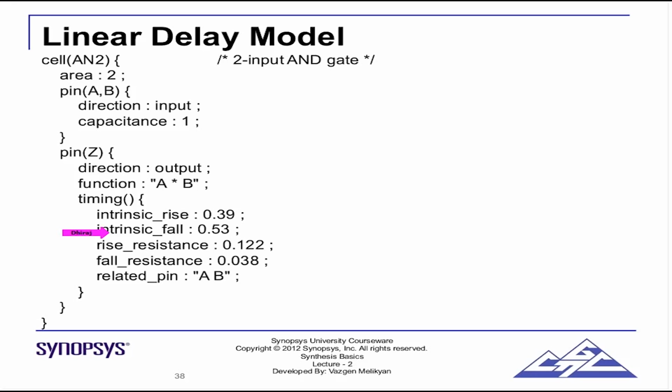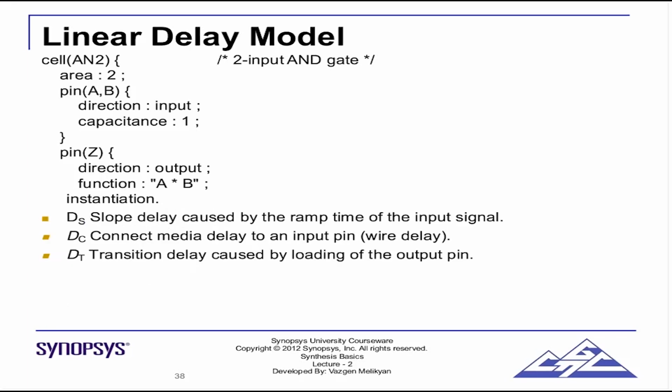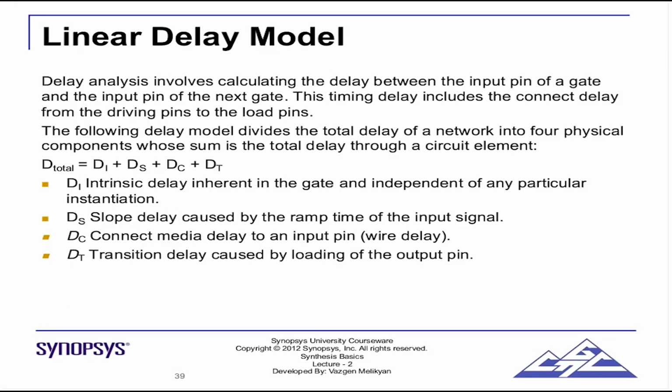Now let's see how these values are used. There is a rise resistance also, there is a fall resistance also. These two will also determine something. Let's see how it is used. In a linear delay model, the process of delay analysis, or the delay calculation, involves calculating the delay between the input pin of a gate and the input pin of the next gate.